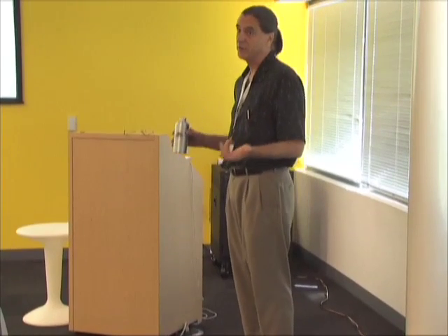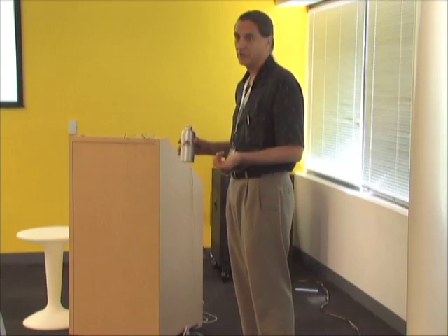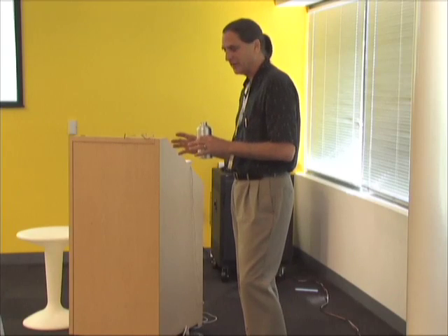The bigger problem in modeling, I don't care whether it's AutoCAD or SketchUp, is that you need to lock geometry you're not using. It's a feature that many people don't use. I was working on a project in 2000 and we were doing it in AutoCAD in Germany, and we had broken the plant down into 13 areas, and we had 13 central models. We had progressed up to about the fifth area in detail, and someone had moved three of the other areas in the background. It's like we didn't understand about locking layers yet.